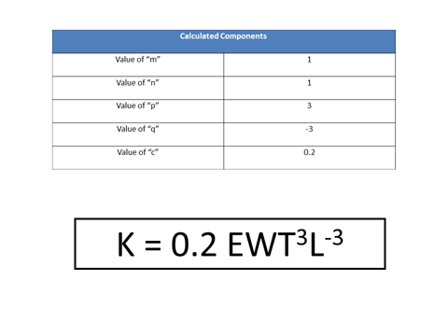The results of the polyfit data and the C value calculations are shown in the table. The final resulting equation is shown in the third box. This completed equation would then be used to mathematically predict load or deflection based on beam properties.